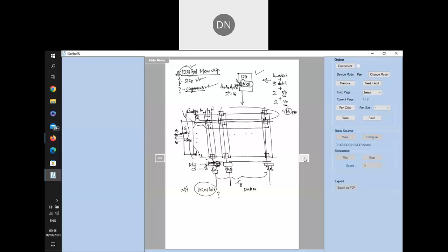Now we have considered a little larger memory compared to the previous. The previous was only 128 bits. Now I have taken 1 kilo, 1024 bits. So this circuit, we will assume, is organized as 128 into 8. See, in the previous case, it was 16 into 8. Now 1 kilobit is organized into a 128 into 8 memory. This is a different one; let's take the other organization now. Depending on the size, we are able to organize it. In this case, it's easy to understand.